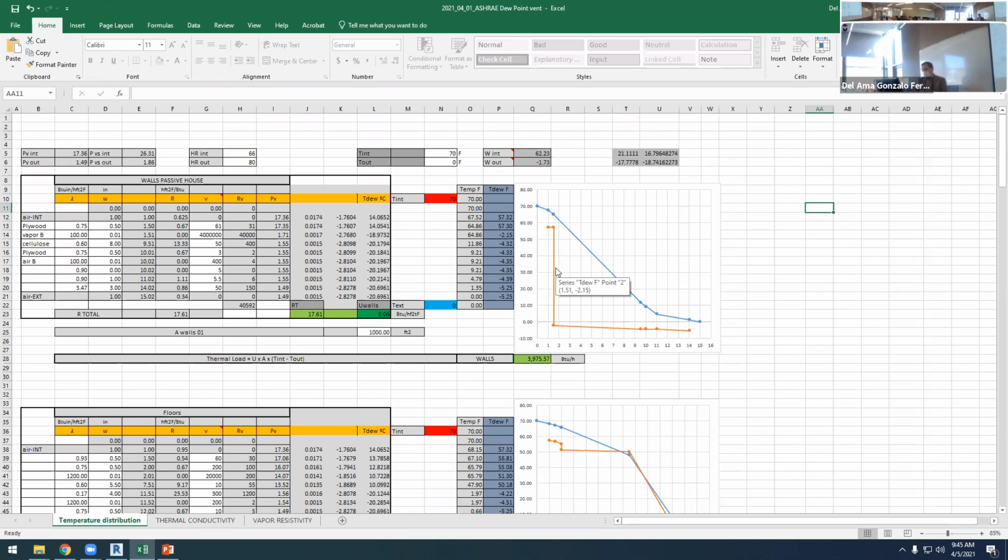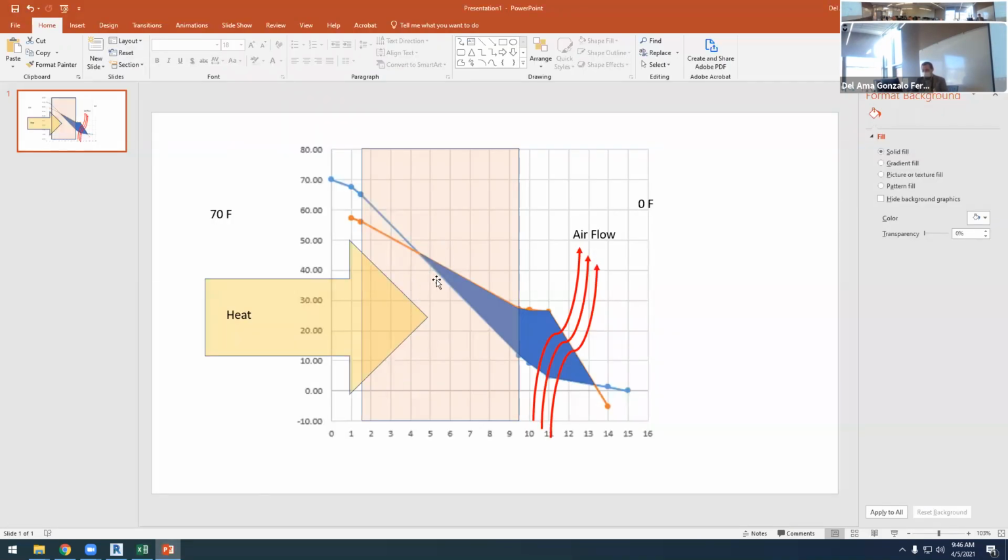But if we are working in a workshop and we get our prefabricated panel and we place it, it's easier having these kinds of things. But it depends. Anyway, the theory is that using a vapor barrier inside the thermal insulation works. The reality is that even if it doesn't work, even if we have condensation, there's a likelihood that it's not important because we will end up drying this out. Yes, but again, this is not under our control.